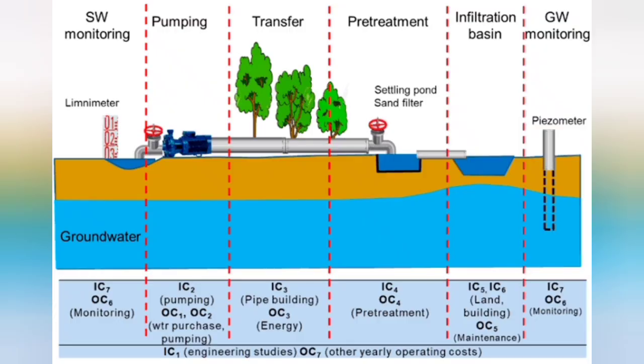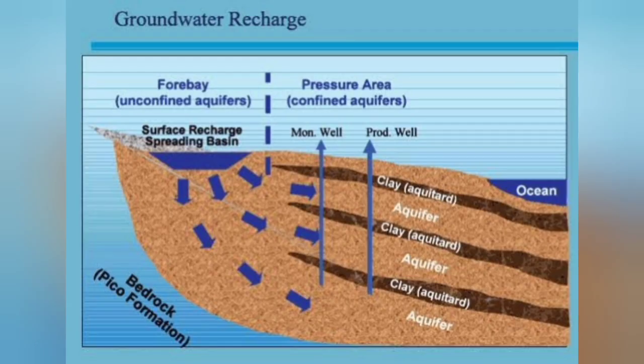providing an inverted filter consisting of fine sand cores or coarse sand and gravel at the bottom of infiltration pits. Trenches are very effective. Clogging by biological activity depends on the mineralogical and organic composition of the water and basin floor and upon the grain size and the permeability of the floor. The only feasible method of treatment developed so far consists in thoroughly drying the basin.